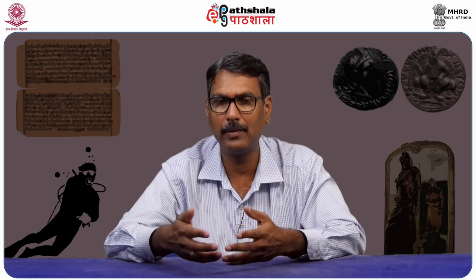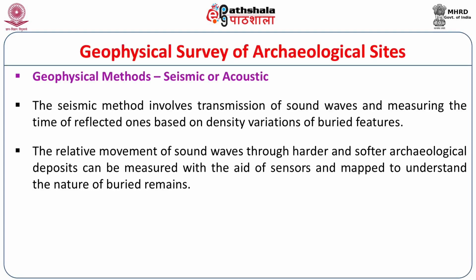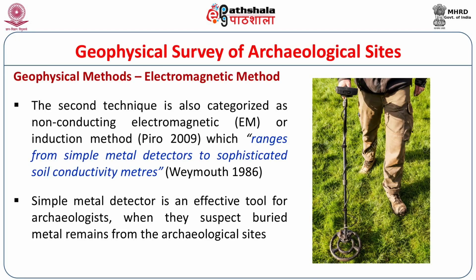Depending upon the variability in the density, these sound waves reflect back strongly or loosely based on the physical properties of the buried features. So the relative movement of sound waves through harder and softer archaeological deposits can be measured with the aid of suitable equipment and mapped to understand the nature of the buried remains. So this is one of the methods used for geophysical investigations.